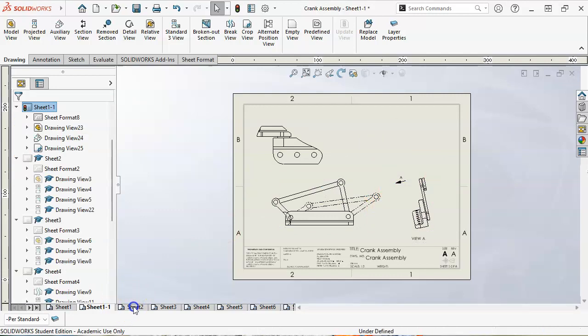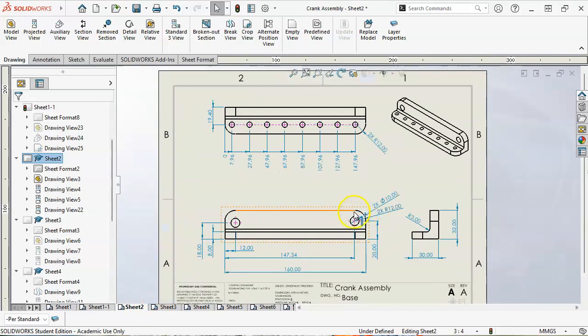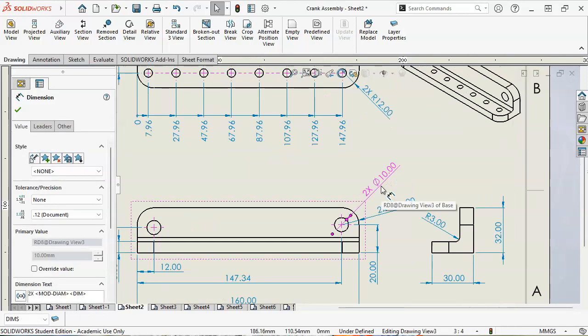And we can move those guys around. All right, so on the tolerances then, it comes back to when we start thinking about fits. If I want this to be a press fit, and I usually think of these in terms of inches to run my tolerances, so I'm sure I will get a decimal place off somewhere here. So 10 millimeters designed at 10 millimeters on the shaft and 10 millimeters on the bore is a line-to-line fit. There's no interference, there's no assumed clearance there.